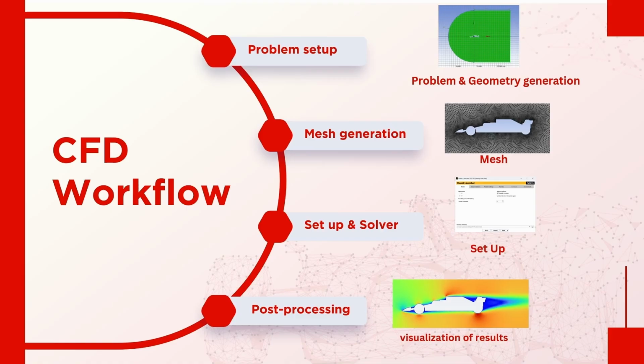The CFD workflow includes creating the geometry, generating the mesh, setting up boundary conditions and physics models, running the solver, and finally post-processing to visualize velocity, pressure, and flow patterns.